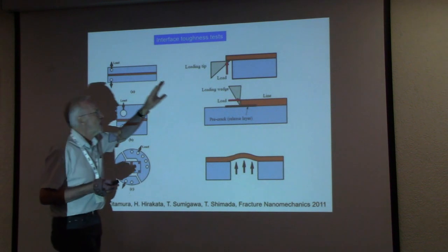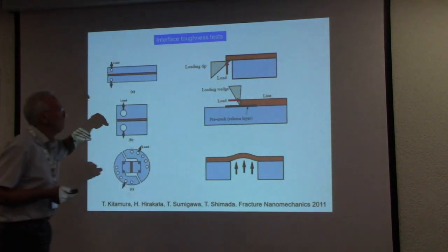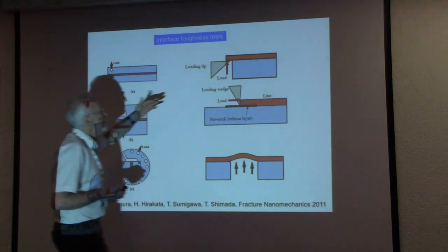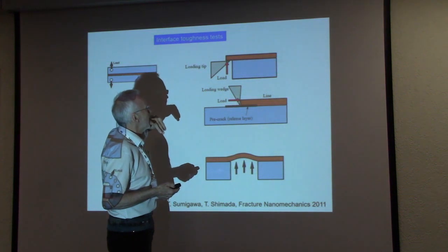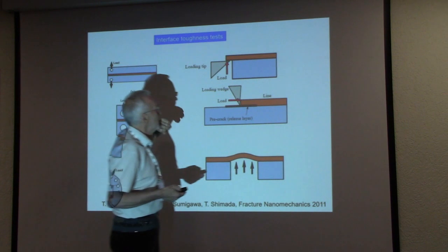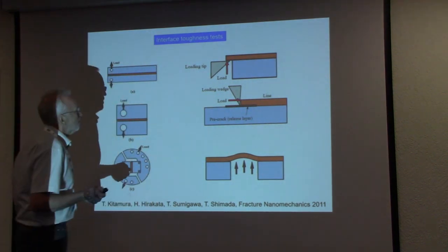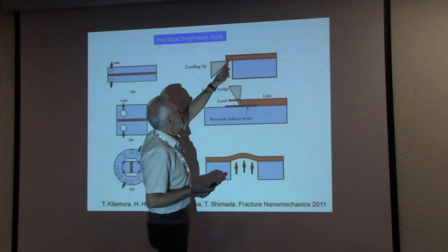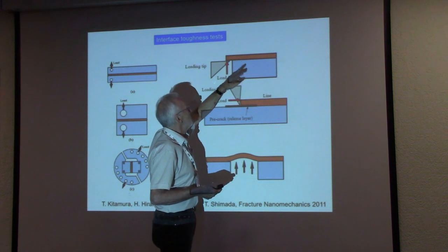These are typical micro sample techniques, where you simply try to realize such a fracture mechanics experiment by simply etching away, for example, the silicon and removing it, then applying a nano indenter and trying to measure the strength.